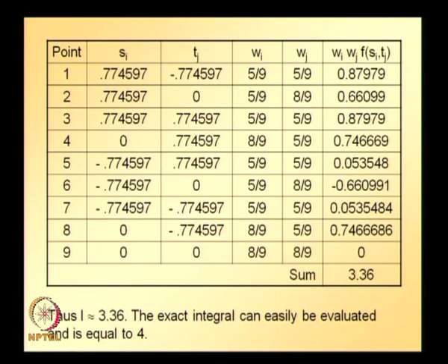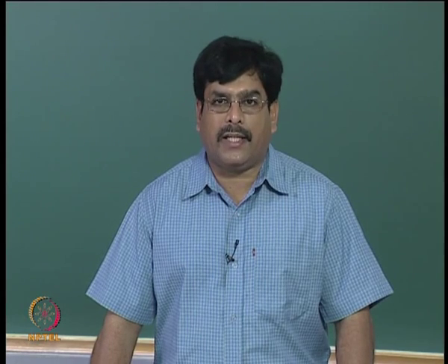And if you see this integral, in the s direction we have highest power as 7, in the t direction highest power as 6, and we can as well apply the formula that we looked at when we were discussing one dimensional integral, that is n point Gaussian integration can integrate a function of order 2n minus 1 exactly.